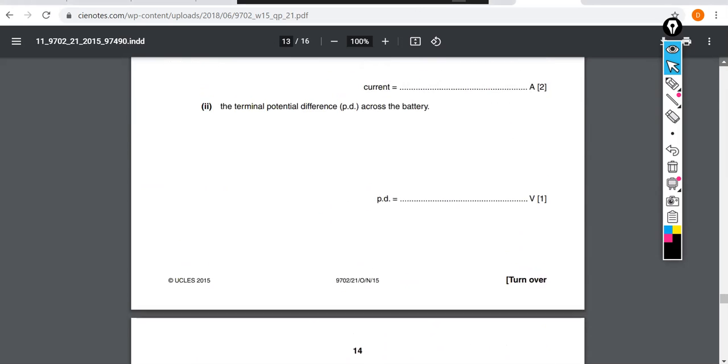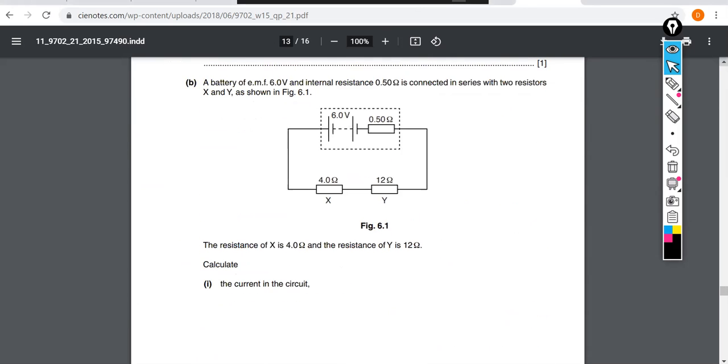So the power developed in the external circuit in figure 6.1, what do we know about it? Well, the external circuit is this. So we're not talking about the internal resistance, right? The external circuit is here. What's the power developed in these two resistors? Well, we could calculate the power developed in this one. We know that the current in this circuit was 0.36 repeating, right?